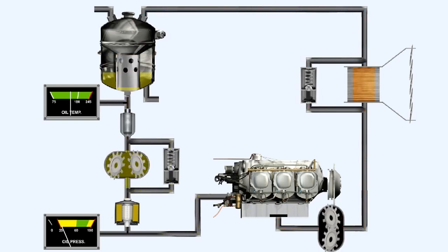Large fluctuations of the oil pressure gauge needle, on the other hand, will probably be caused by insufficient oil in the system. The engine may have been leaking oil, and eventually the level will drop to a point where the pressure pump cannot sustain its output. Then the pressure will drop momentarily until the pump can get some more oil, when the pressure will rise again, if only for a moment. If the minimum oil pressure cannot be maintained, then the engine must be stopped to prevent damage.